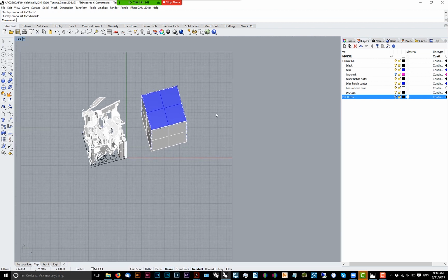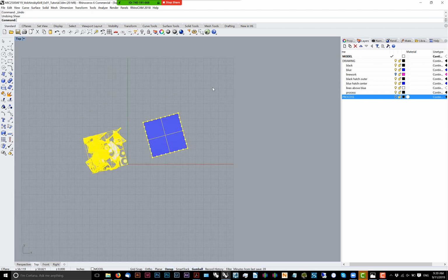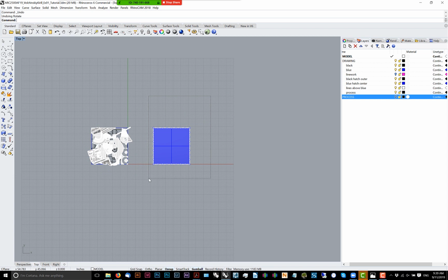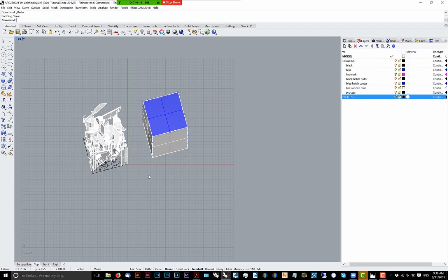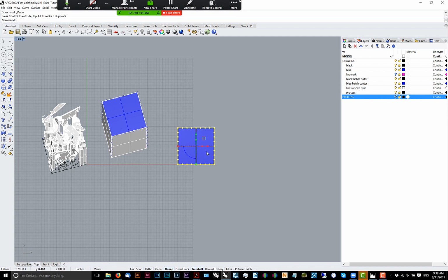So I'm going to keep it at this. Always copy your geometry. For example, if you decide to try a different projection technique, it's good to have a copy of your geometry, whatever it is, so that you can try something different on it.